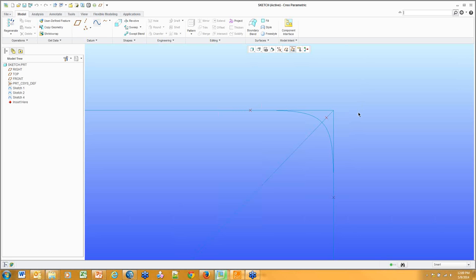Otherwise, all other operations are called the same thing. Maybe we have some SolidWorks users out there. That's fantastic, because whatever you call something in SolidWorks, let's say you're looking for a loft. Creo does not have a loft. Creo has a sweep. So if you were to type in loft or type in fillet in this area here, you would find Creo pointing to what it is called in Creo. So the ramping up from going from a SolidWorks proficiency to a Creo proficiency is incredibly short. I cannot demonstrate that, as that is a configuration option, and if I change that, then I can't find the Creo option. So you have to change a config option for that, but it's very easy to do.